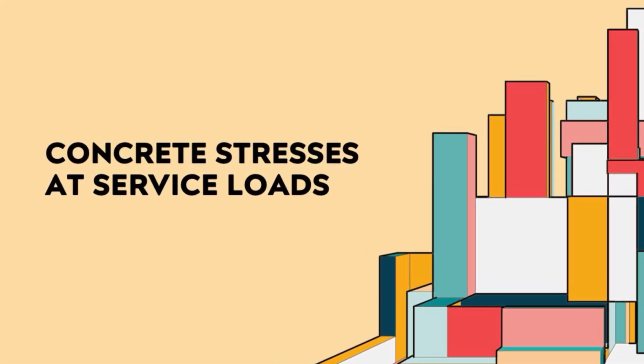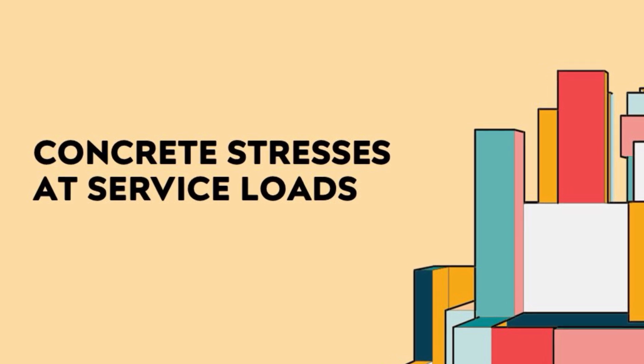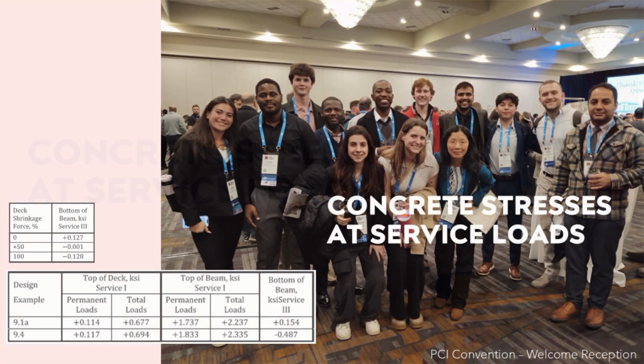Now that we determined the beam can withstand all the stresses applied during transfer, we have to check all the service loads as well. The process for checking the service loads is similar to that of transfer loads. First, you need to determine the allowable compression and tension loads for the beam. Then you need to determine if the actual stresses at both the top and bottom of the beam are less than the limit state. The compressive stress due to fatigue also needs to be checked to ensure it is less than 40% of the concrete compressive strength after losses.